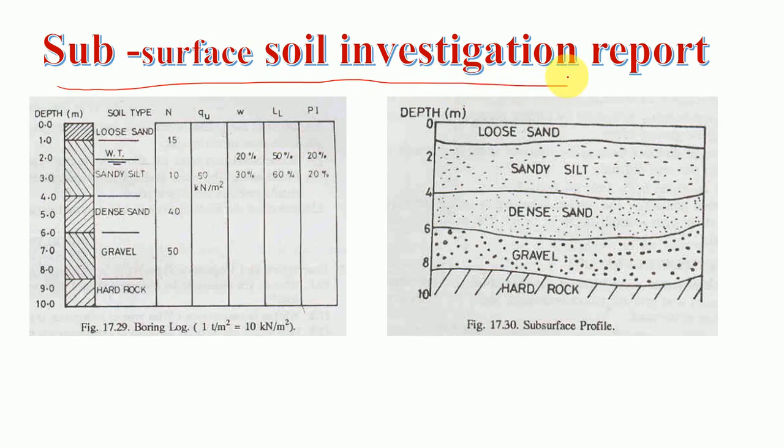After performing our soil investigations, both the in situ tests and the engineering lab tests, we have to prepare the soil investigation report. In the soil investigation report, we have two parts: one is the boring log, and another is the subsurface profile. In the boring log, we have the depth, the soil type, and the soil penetration value at particular depths of the subsurface,